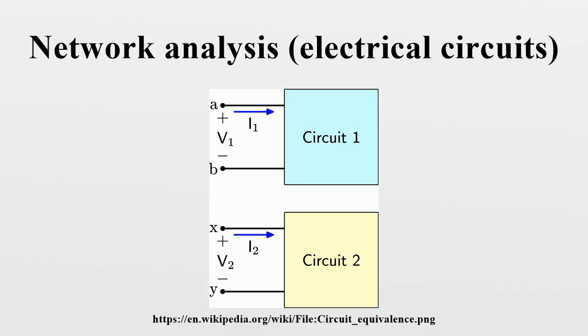However, this is rarely done in reality because, in many practical cases, ports are considered either purely input or purely output. If reverse direction transfer functions are ignored, a multiport network can always be decomposed into a number of two-port networks. Distributed components. Analysis using two-port networks is a matter of choice, not essential. The network can always alternatively be analyzed in terms of its individual component transfer functions.